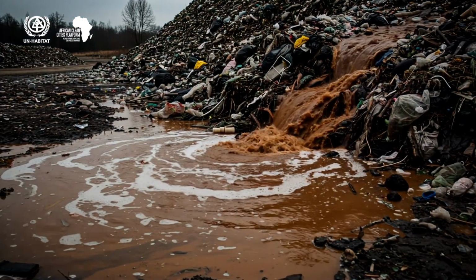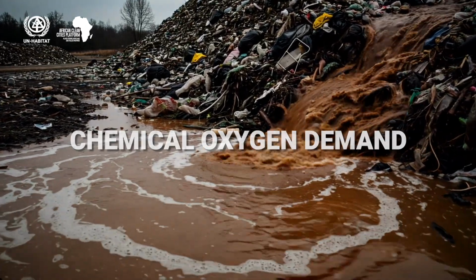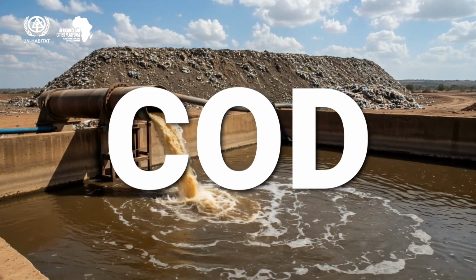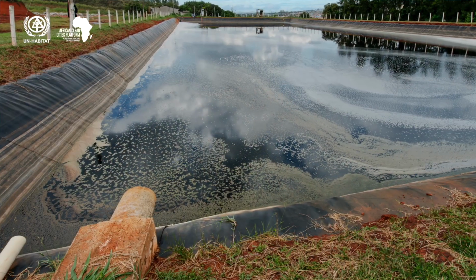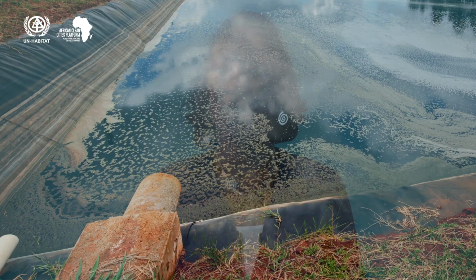Scientific tests carried out have shown that semi-aerobic management can treat leachate pollution more quickly than anaerobic management. Here, chemical oxygen demand, or COD for short, is one of the key indicators to illustrate water quality. The lower the COD figure, the better the water quality. But, as I mentioned earlier, we cannot leave it at that. Further treatment is needed for this, and we need a leachate treatment pond.